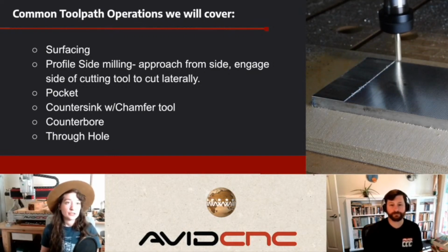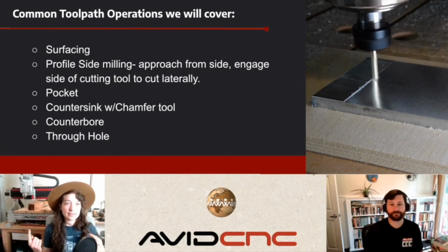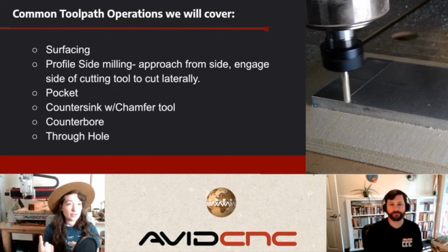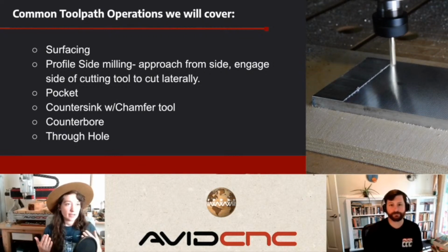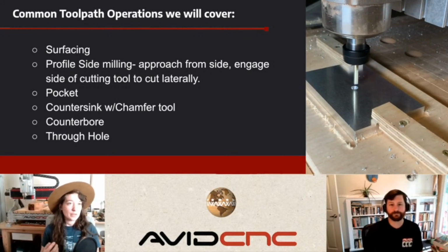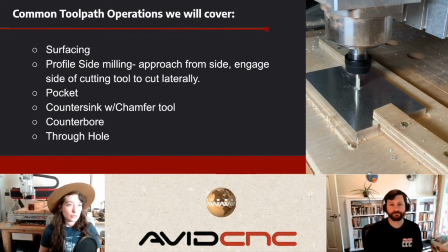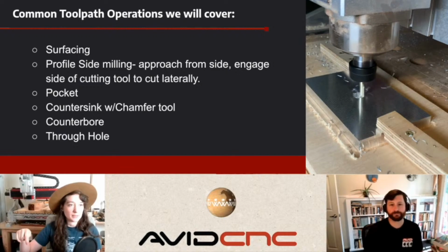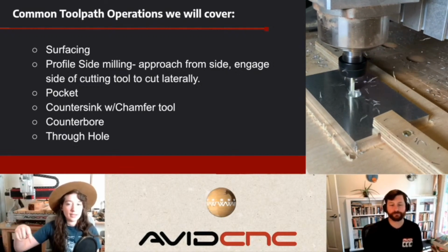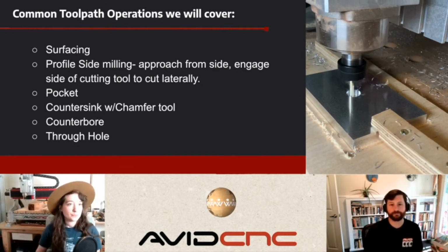Profile side machining. When you want to engage the side of the cutter to create your profile, engaging the side of the cutter will really help with the cutting tool life, and because you're approaching laterally, it's not having as much of a step down, it's focusing more on the step over.